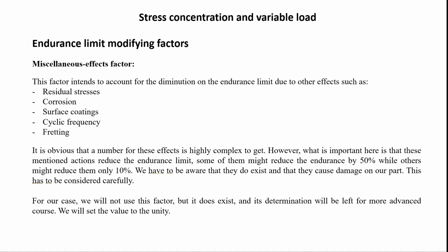For example, if you've seen a little bit of welding design or welding calculation, welding is done by heating up a couple of parts and adding a third material to join them, and that's a lot of energy you're putting there. Then when everything is heated up, it melts, and the three parts are melted and joined. But when it cools down, there are a bunch of stresses that were not there before, because you put in a lot of energy, and not all of that went away. Then you have to do some stress relieving practices to normalize and ease out the higher stress situation in welding so it doesn't break suddenly in that area.